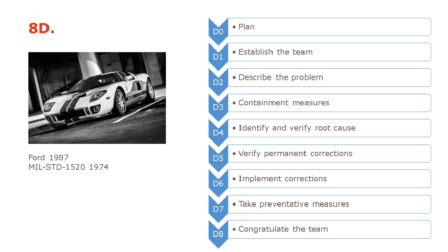So put in problem statements, 5 whys, observing what's happening, what isn't happening. One of the things that's quite specific to the 8D process is the containment measures. So that's about trying to protect the customer or the end user from whatever this issue is. So can we put some temporary things in place that allow us to minimize that effect?